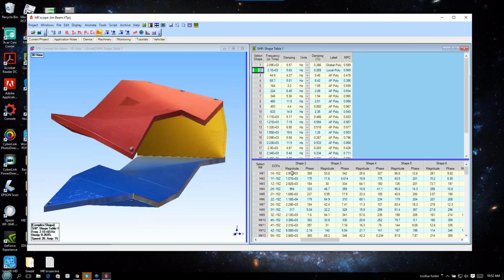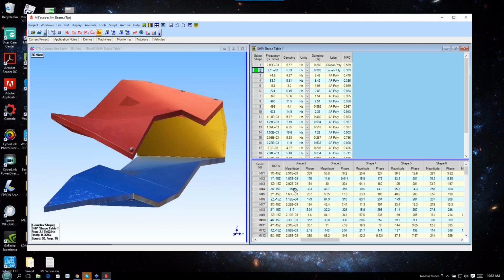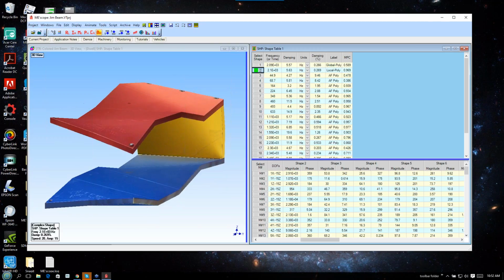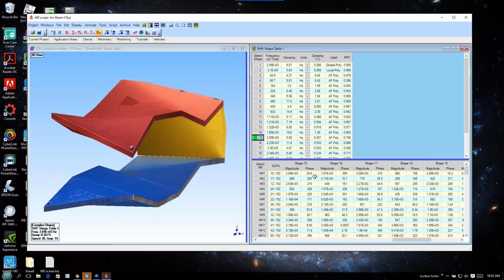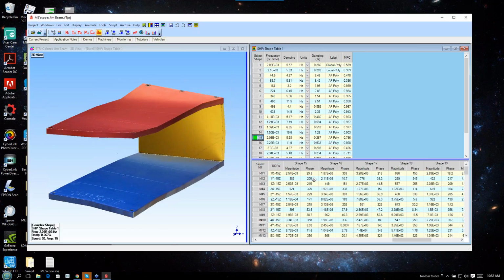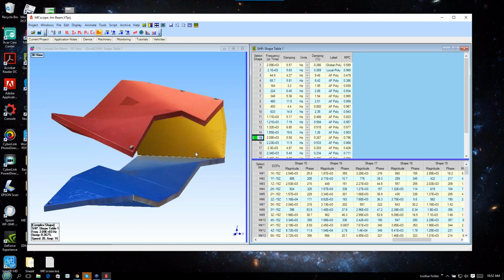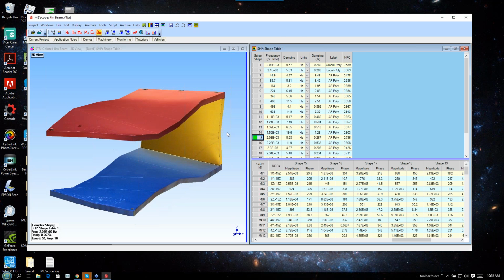You have to look at the magnitude along with the phase. So when we're down in the noise, the 954 here, the 330 is not going to show up as much in the animation. Now if I go to the stability fit, you can see I've got phases that are 30, 205, 215. That's why this animation is showing a lot of complexity.